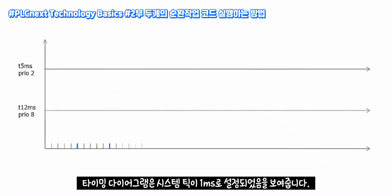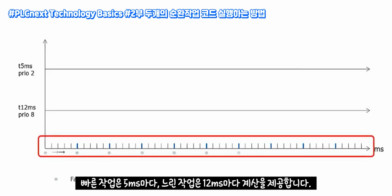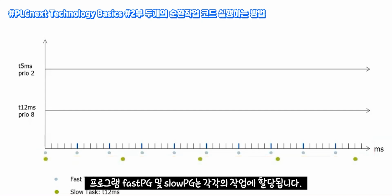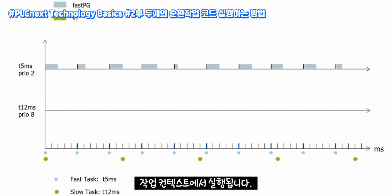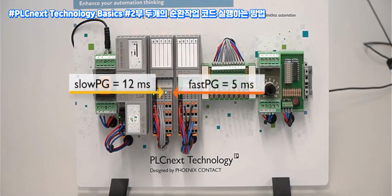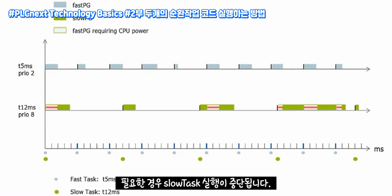The timing diagram shows that the system tick is set to 1 millisecond. The fast task provides a computation every 5 milliseconds, the slow task every 12 milliseconds. The programs fast PG and slow PG are assigned to the respective tasks. They are executed in the context of the tasks. If both tasks require computation time simultaneously, the fast task will be executed with higher priority. If necessary, the slow task execution will be interrupted.